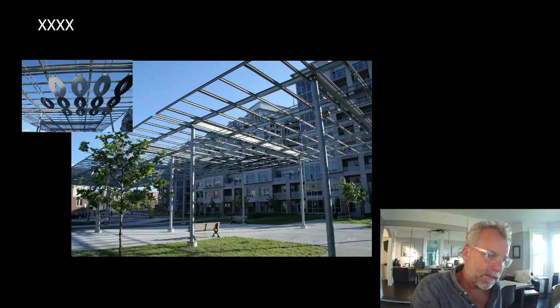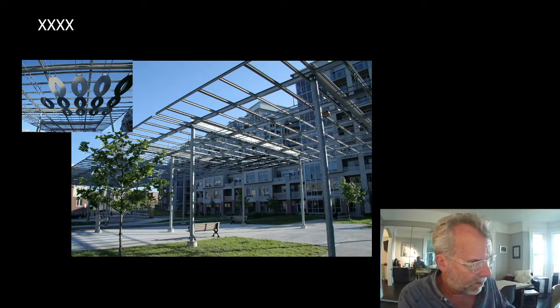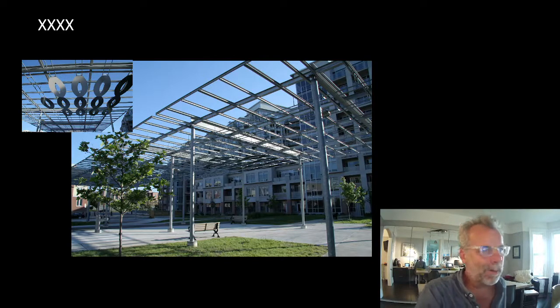The artist told us that it would have retractable awnings on it, and that the awnings would be retracted under high winds, and therefore it didn't need to be designed for snow, did not need to be designed for high wind loads. It was to be designed for very nominal loads. We said, we hear you, but we don't think that human intervention is an adequate safeguard for life safety. We need to design this for high winds.